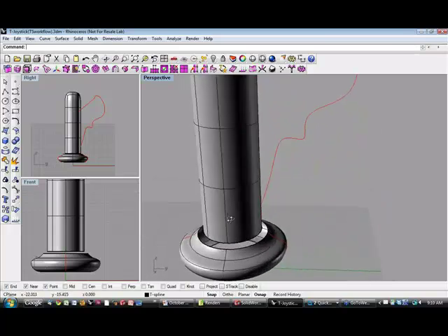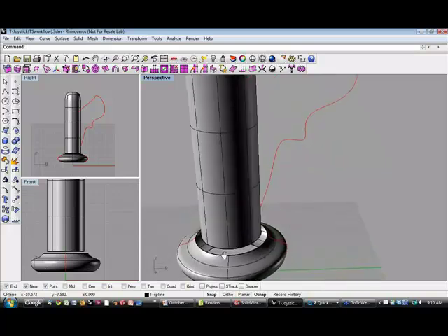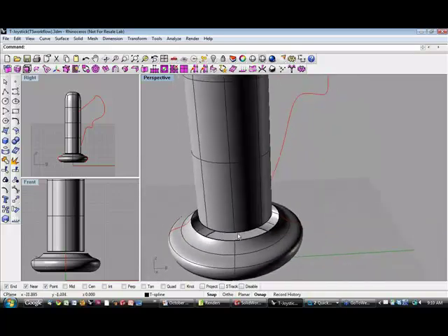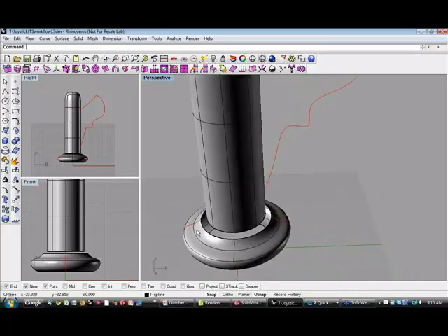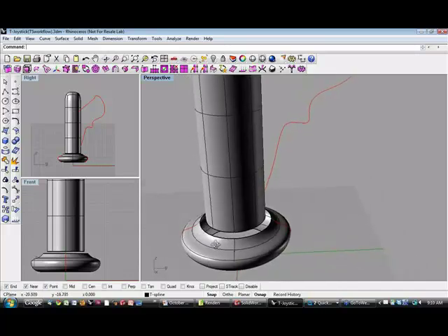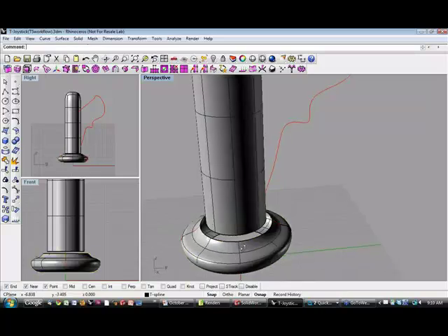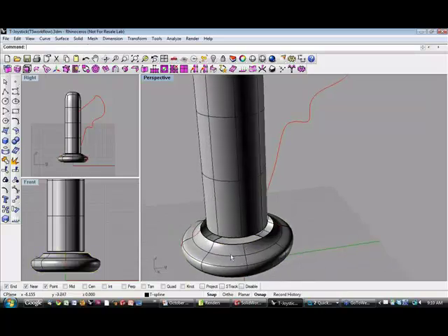And now we'll go ahead and merge the T-spline surface to the NURBS surface. To perform the merge, first we need to convert the NURBS to T-splines. And before we do that, I'll go ahead and rebuild this NURBS surface to make sure that it's degree 3 by 3. And then I'll also make sure the point count stays 8 by 8 so that the isoparms line up with the T-spline surface.